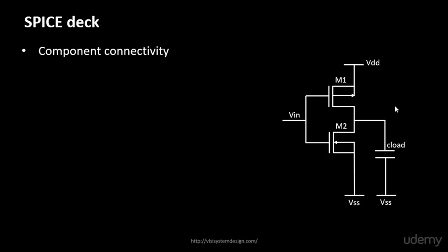There are a lot of equations and a lot of theory behind the computation of this particular load capacitor. But in this case, we'll assume a load capacitor value, let's say 10 femtofarads, and move on. In the advanced courses, we'll look into how exactly we get this load capacitor. It is basically decided by the input capacitances of the circuit which is connected at this point.